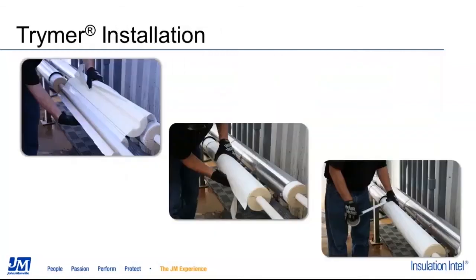For installing Trymer insulation, I would like to point out a couple of things. The first one is that when fabricators are machining the pieces, there's also an opportunity to get a factory pre-installed vapor retarder, and that's what's shown in the figures here. And the vapor retarder would actually have the SSL tape, so very similar to the way our Microlock HP insulation comes in.